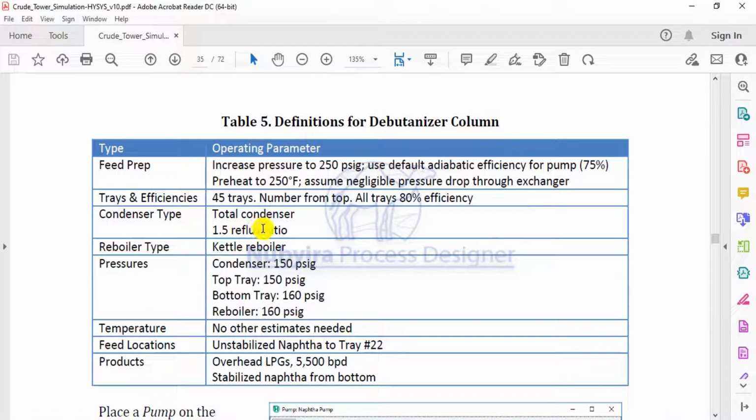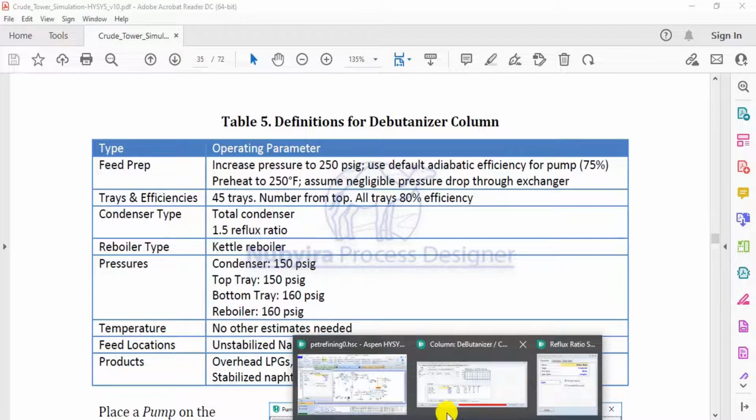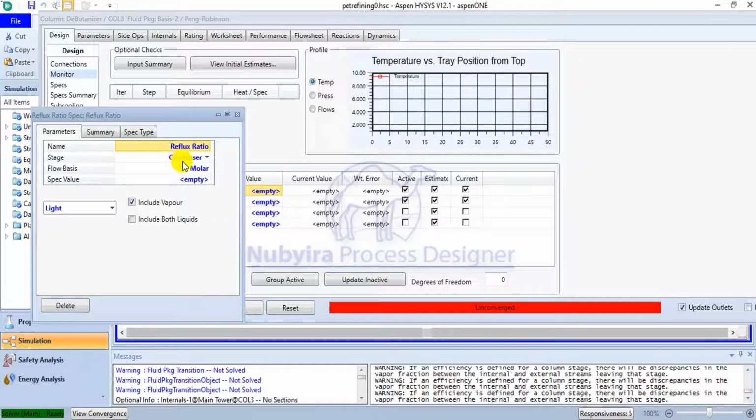Okay, I'm going to make it to be, they mostly specify the reflux ratio in molar basis. So I'm going to make it to be in molar basis, although they didn't actually give us a value here, but the best is to use the molar basis that they have in here. So the stage here, we have the reflux based on which liquid you can choose, maybe just vapor and water stream. You understand? So I'm going to specify it to be 1.5.